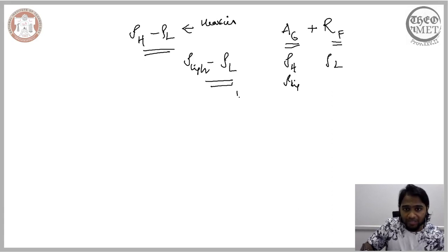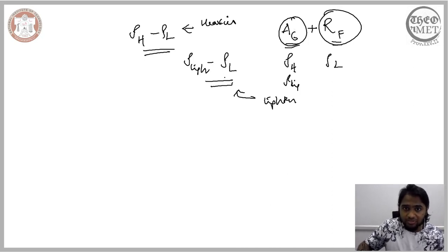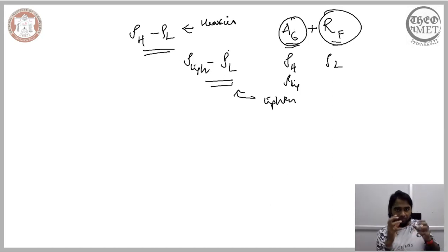The behavior of the lighter particle in a given medium, when you have the combination of accelerating and the resistive force, is influenced by this term here. So whenever you want to quantify the behavior of a heavier particle or the lighter particle during gravity separation in a given medium, you need to consider the density of both the particle and also the density of the medium, because it is through the density of the medium we are accounting for the resistive force. So essentially these two terms govern or dictate the behavior of the particle in the medium under the gravitational force.